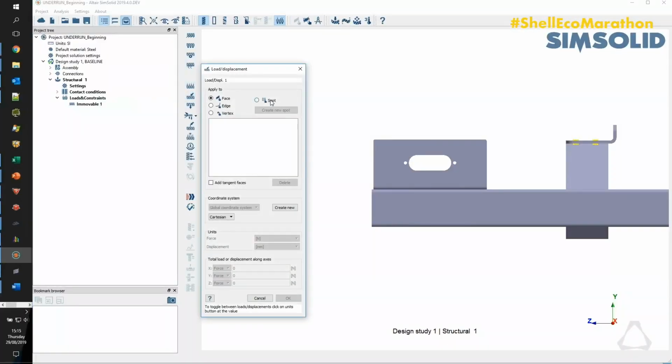So there is a marked difference, a fantastic difference. We took the SimSolid results and were able to submit those results to the DVSA, who then physically tested it, and we found that they were within approximately 1 millimetre of the deflection that had actually happened. So it was a really, really good tool for us.